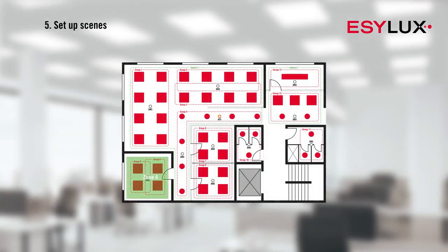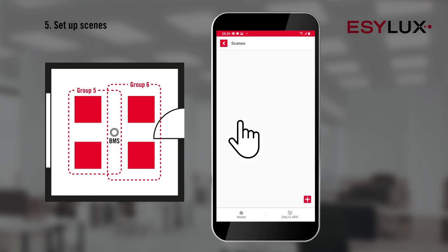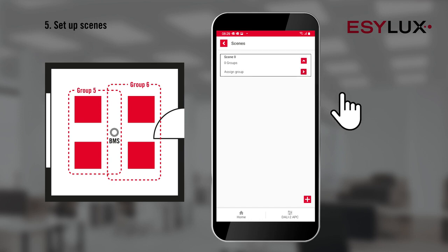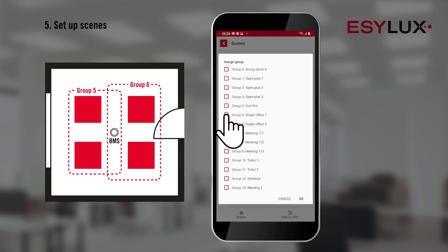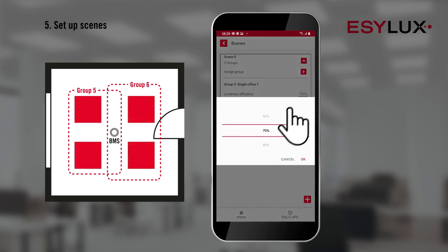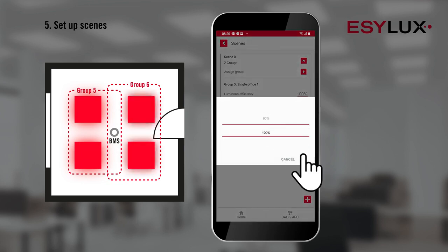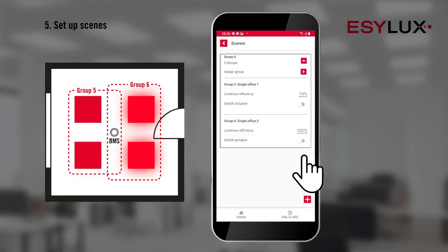The Easy app also allows you to configure light scenes easily. Let's take a look at Zone 4 to see how it works, the control room. Under the Scenes tab, you can set up various configurations. Create a new scene and assign the groups 5 and 6 in this case. Then design the scene, for instance, with 100% light output for concentrated working. All these settings can also be changed again at any time after installation.